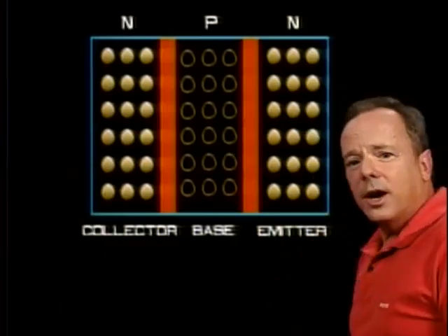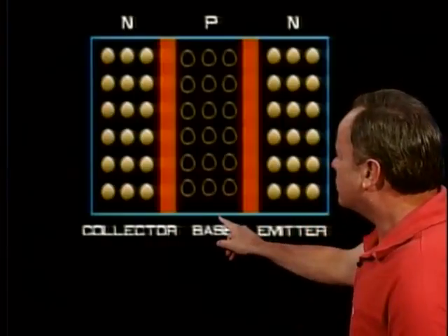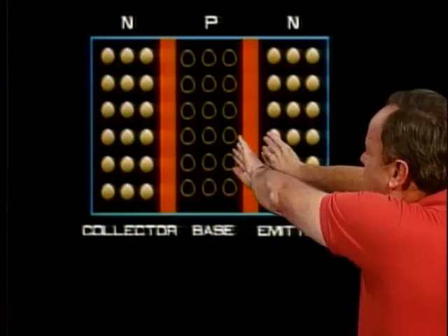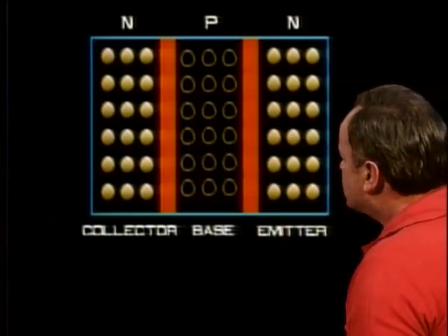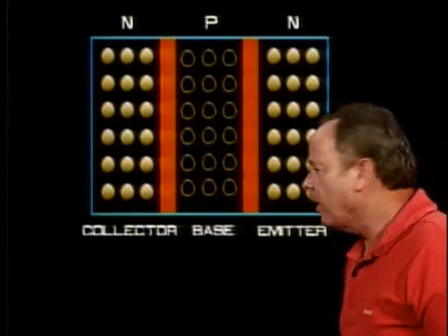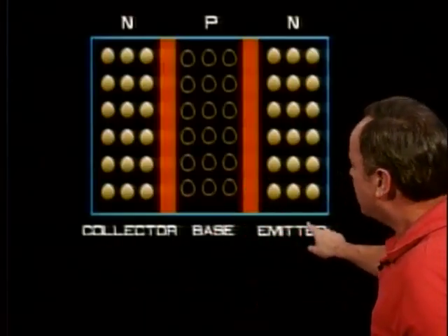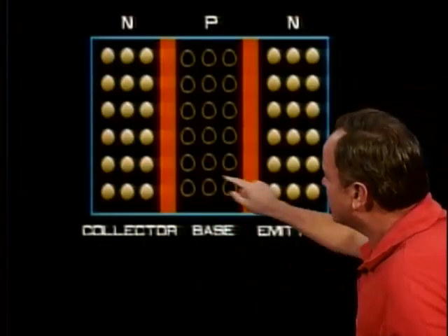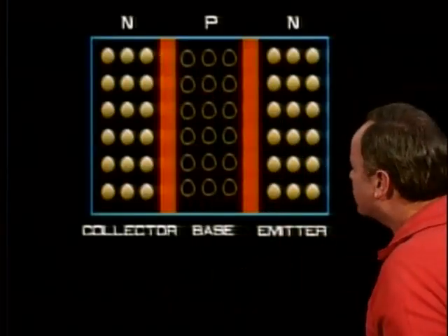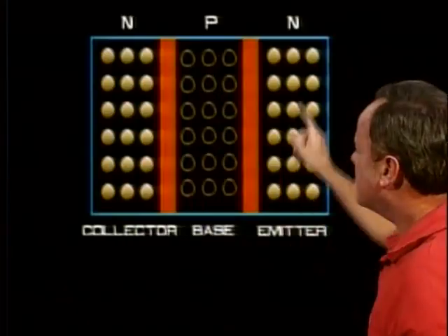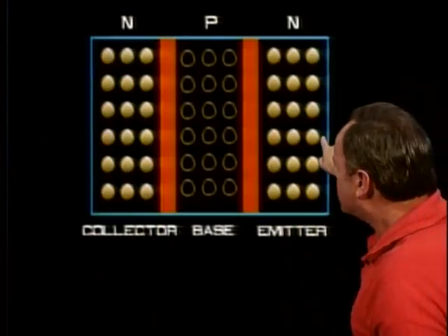If, on the other hand, it was the other way around, and you had a positive charge here and a negative charge here, then the electrons would be driven away from the junction and the holes, and the electrons could not flow across here. So in order for electrons to flow through a transistor, the base has to have a different charge than the emitter. The emitter has a negative charge here. The base will have to have a positive charge in the case of an NPN type of transistor, and then electrons will flow across. So this is an NPN transistor.